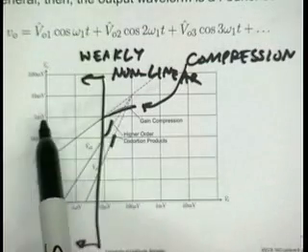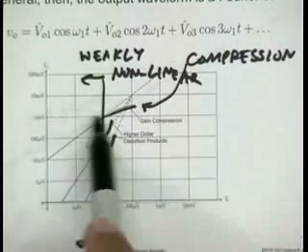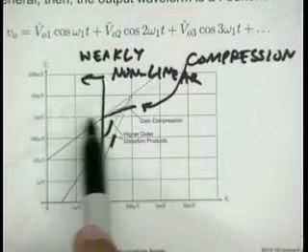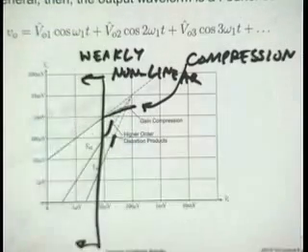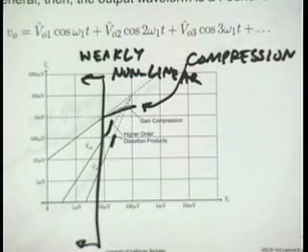So in this case, let's say, this is a pretty wimpy amplifier if it compresses at 1 millivolt. But let's say eventually at supply voltage it has to compress, right? It can't ever swing above supply unless there's really weird stuff going on in your circuit. Okay? Don't want to make a general statement, but for most circuits, you're going to compress eventually.